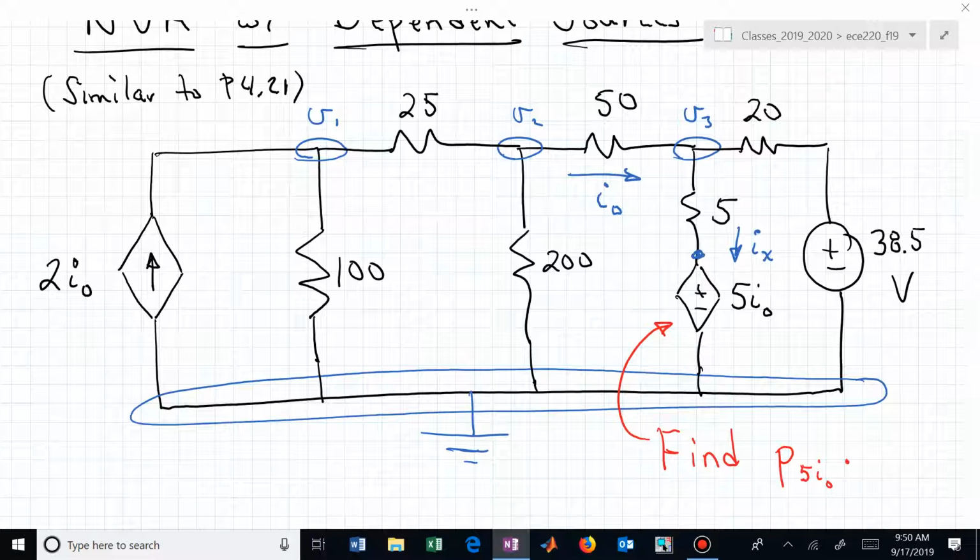Isn't that the voltage times the current, and what's the sign on that expression? Positive or negative, based on the passive sign convention? Positive, because the current's hitting the positive terminal that we have labeled before it goes through the element. And what does that mean? That means whatever that product yields is the amount of power absorbed by that circuit element. If the result ends up being negative, absorbed, then you really have that magnitude of power supplied to the rest of the circuit. Or delivered, or I think the book even says developed.